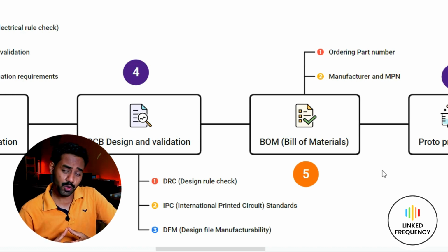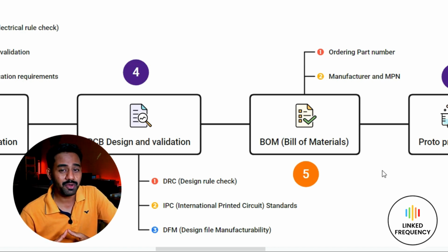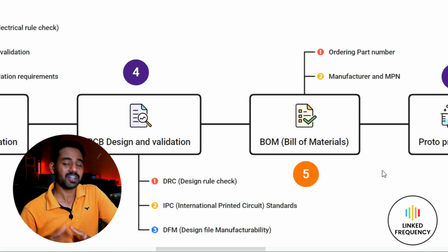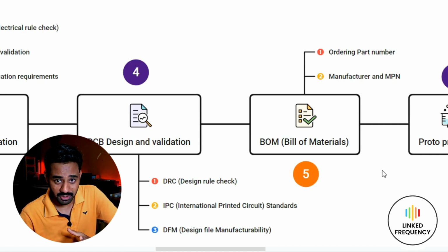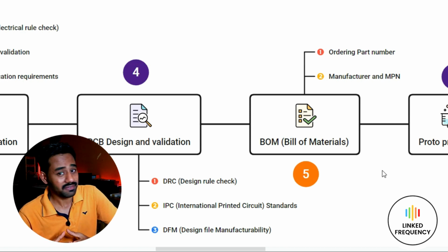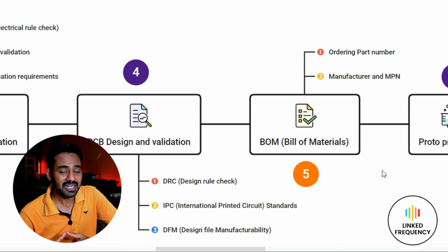Bill of material is going to be one important stage where you get to know the price point for your entire product development. Say for example, if you are using a 7805 regulator in your circuit, then the ordering part number of that particular IC is defined in the bill of material. We all know that 7805 is a general number, but LM78M05 is one part number which we need to order when we are ordering this kind of component from our vendors.